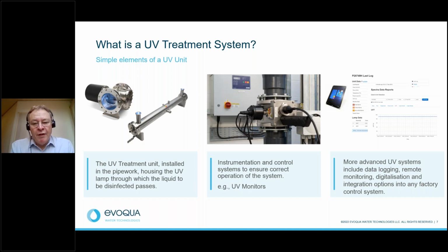So if the filter efficiency is dropping and organic loads within the system are increasing, then you'll see that in the UVI sensor. So the review of UV data can help optimize other factory treatment stages as part of an integrated facility. And this is the sort of thing we see becoming increasingly relevant in the future. More and more processes are going to become more efficient by harvesting big data. So again, ensure that when you're looking to select any kind of process device, that interconnectability is built into those things so they can actually talk to other devices within the factory.